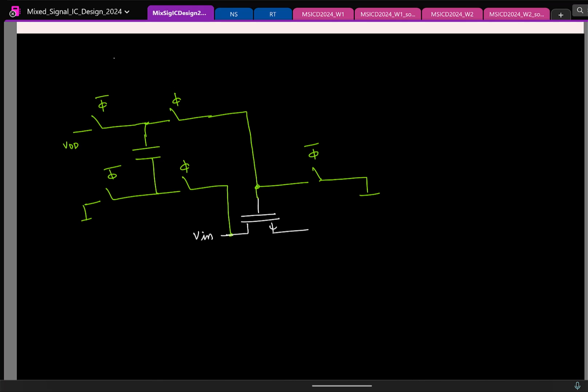Cool. So let's start to see. Let me actually label the switches, or let's start with this switch. This switch is basically trying to pass ground to my gate. What kind of switch can I use here? NMOS. As of now, we know only 3 candidates: NMOS, PMOS, CMOS. So here it looks like NMOS is a good candidate because it's passing a constant low signal. Fine.